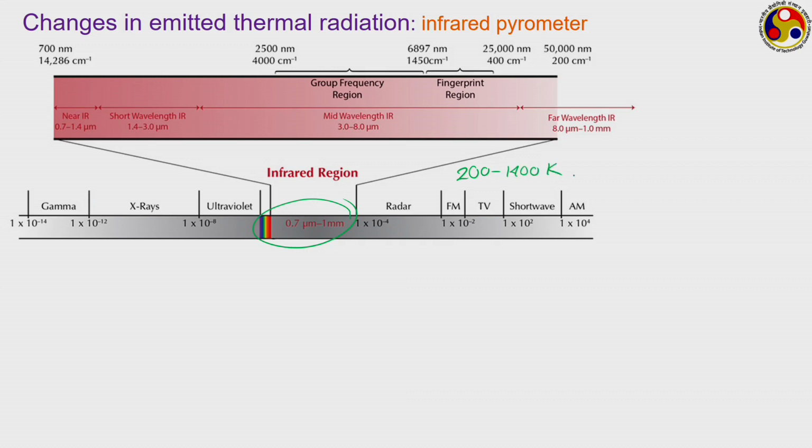So, using infrared, you can easily get temperature values quite close to normal ambient temperatures or something below that 700 degrees Celsius limit that we have seen in case of optical pyrometers. The working principle remains the same, the only difference is that here we are using the infrared spectrum of light. Infrared cameras or infrared image guns are quite popular and very easily available in the market, and you must have seen several applications of this.